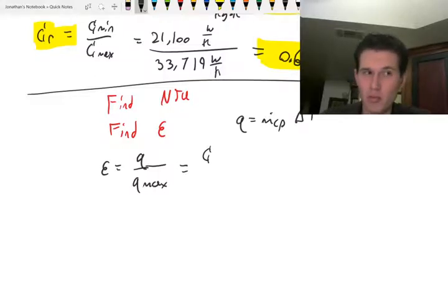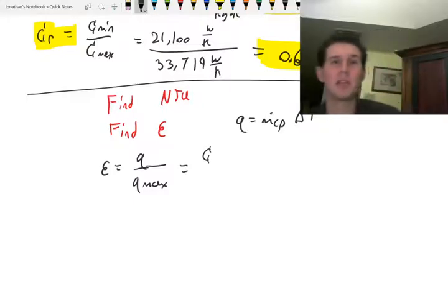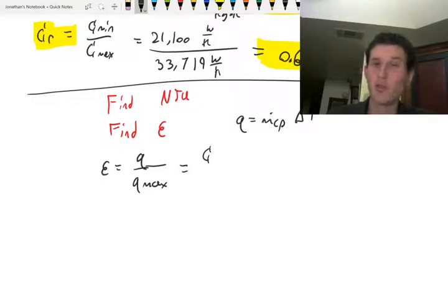So the air coming in, do we know the temperature of the air coming in for certain? Sorta. Yes, we know our maximum temperature that it can be. Great. Do we know the temperature that it has to go out as? Maybe. We stuck a measure down there and took a look, but really it doesn't have to leave at that temperature. How about the water? Well, we know the maximum safe temperature for that water, and we know for certain when we run it through the heat exchanger how cool it has to be when it gets back to the motor. So we know that.